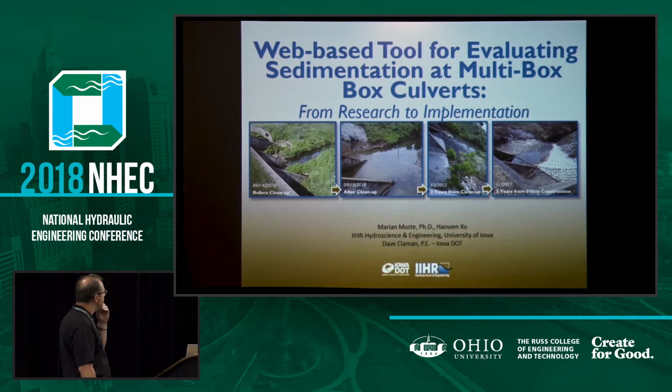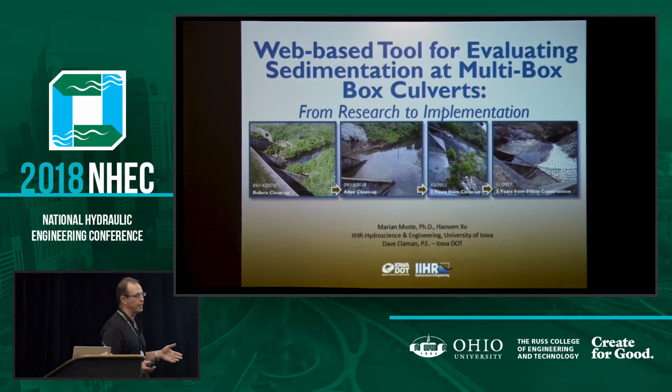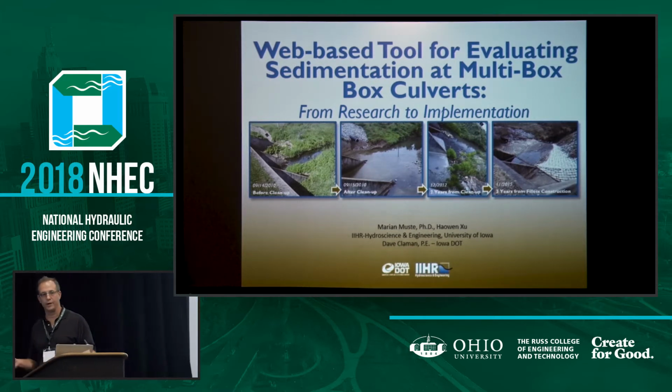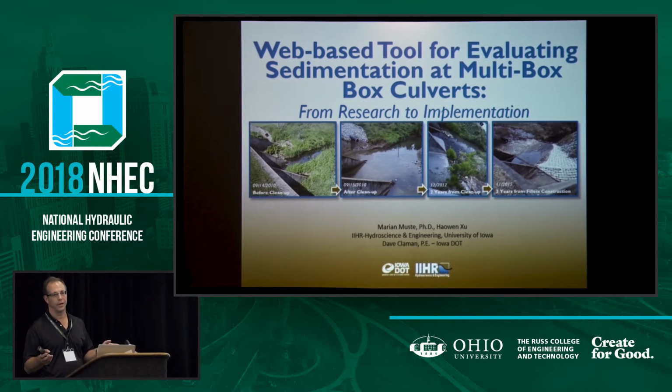I'm going to talk a little bit about how we got to this web-based tool and some of the research we've done in Iowa over, well, about the last 10 to 12 years. And it all started with a common problem that we all have: culverts. We design culverts for hydraulically handling like the 50-year flood or the 25-year flood. So a lot of times that culvert is wider than the channel, right? And if we have a multi-cell barrel culvert, a lot of times those other outside cells start to silt in.